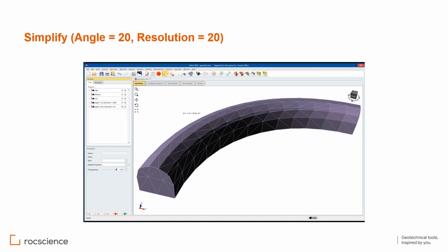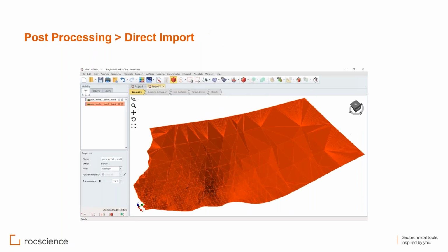So it shouldn't be this coarse either. It should be fine enough. And if you use the default of the software, 99% of the time it's good. These very fine retriangulations have their own specific application that's out of the scope of this presentation.